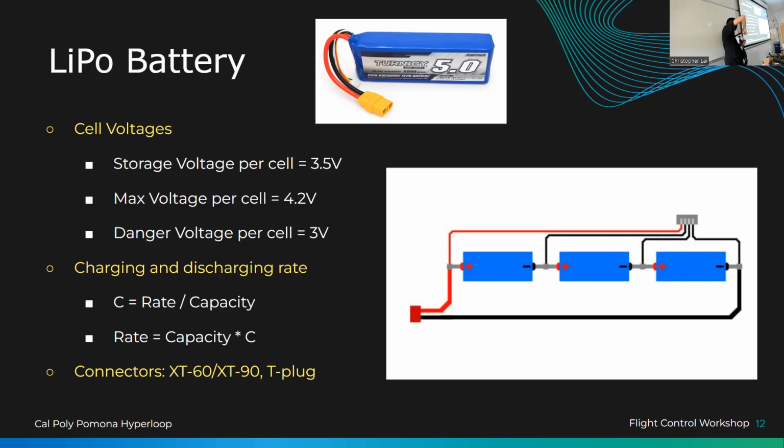If I open it up, you can see that I stored a couple things in my LiPo bag. I stored a charger in case my LiPo batteries run low. And if you guys start using LiPo batteries, I recommend you get one of these chargers. These are balance chargers. They're very good because you can set the charging rate or charging mode, and they will keep your batteries nice and healthy. Because batteries are kind of like a human, right? I also have LiPo batteries in here, and a voltage tester.